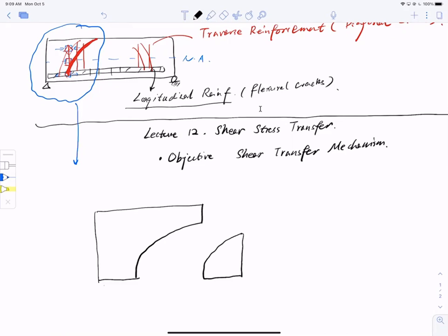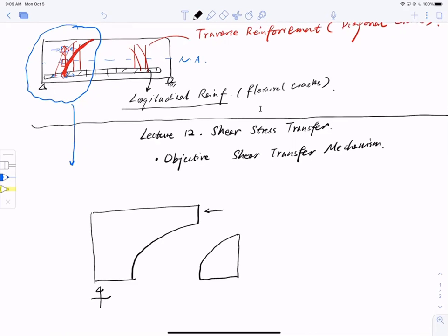And this is my support on the left. So for a free body diagram, I want to do a force decomposition, see what kind of internal forces I have on the cut, right? Naturally I have a compression force here, I call it C1. This compression force is also accompanied by a shear force, Vcy here. And almost in parallel with this diagonal crack, I have a parallel shear resistance force called VA.